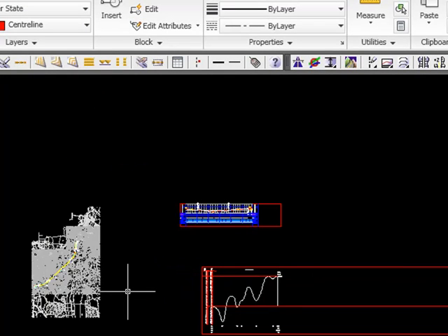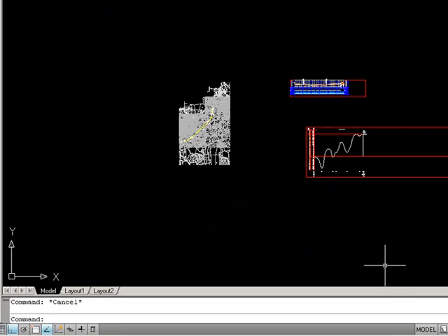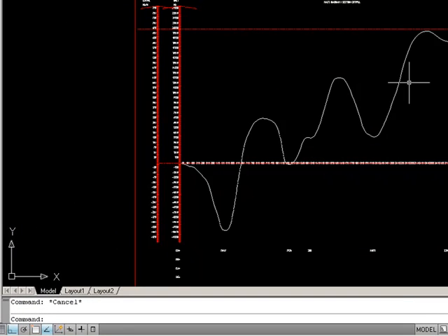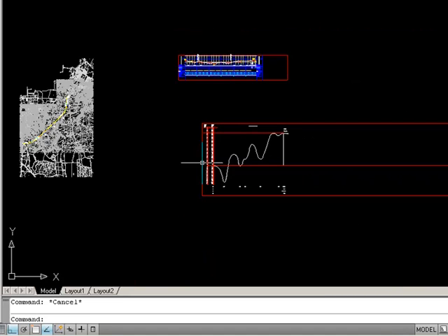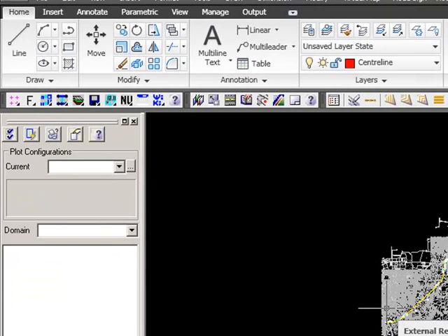Then the next thing to do could be to limit our mass calculation within the road model. Let's say we know that we have a bridge in a certain drainage. We can tell the software not to calculate the volumes on this particular stretch because we don't need to fill when we have a bridge. And that's the next video.